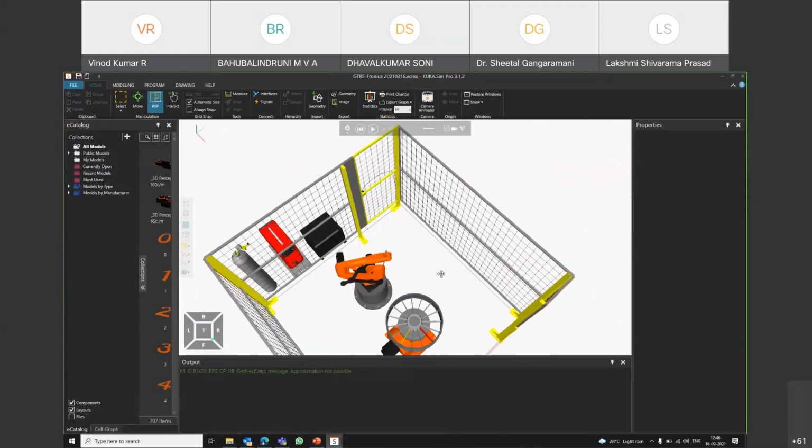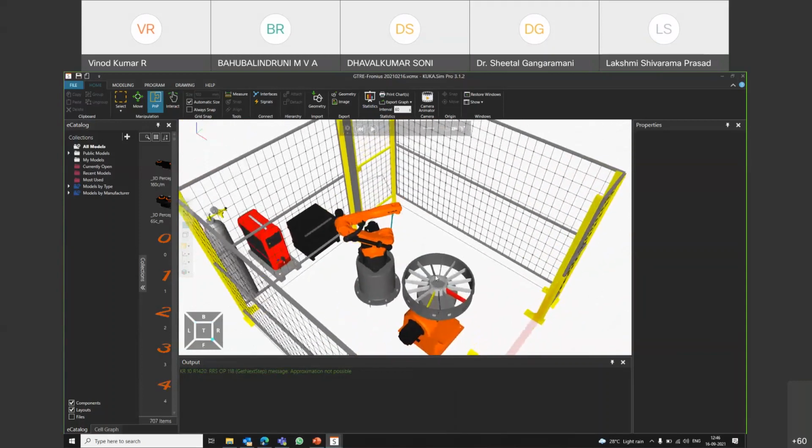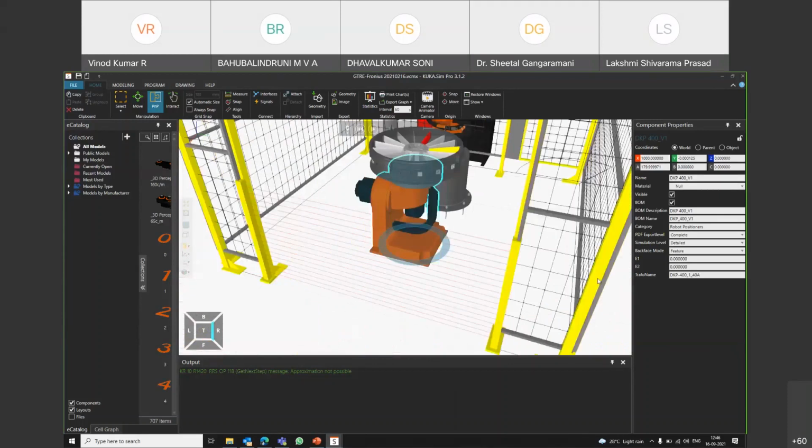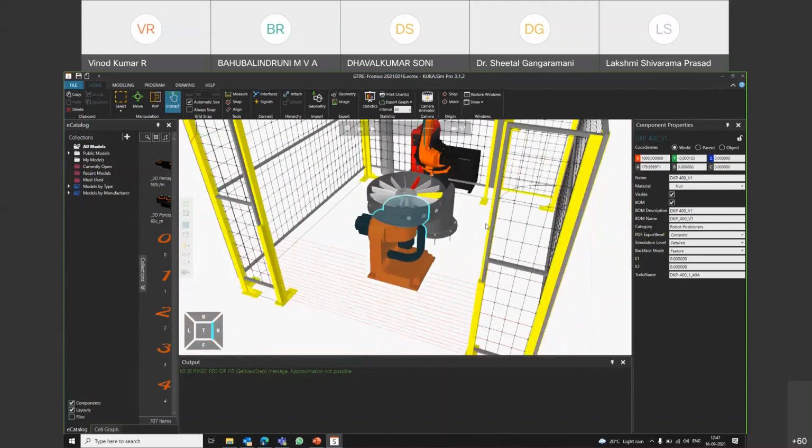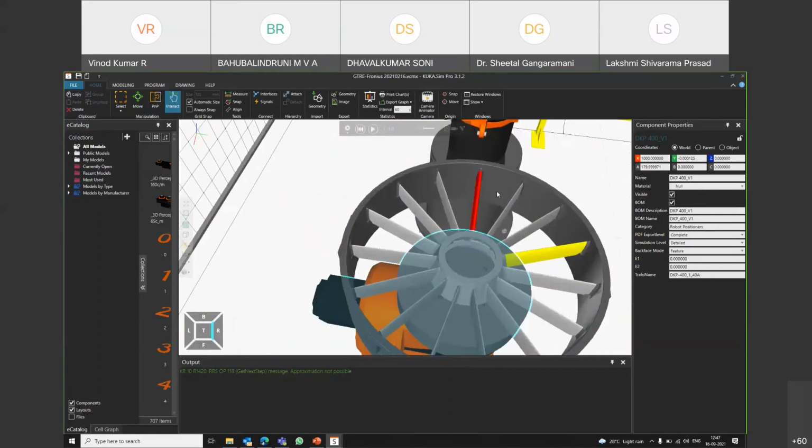This is one way. And now let me show an arc welding application, as I was explaining about different angles to be maintained. So here, it is not only the robot. There are two things in this. Till now we were discussing only the robots. Here we have a positioner. What is a positioner? A positioner is an external axis that is required for this component to move in different angles. It needs to move in this direction, or it needs to rotate like this. This kind of external axis is known as positioners, linear tracks or spot guns. And in this particular case, this complete fin has to be welded automatically.